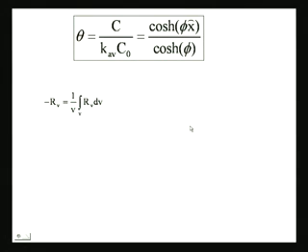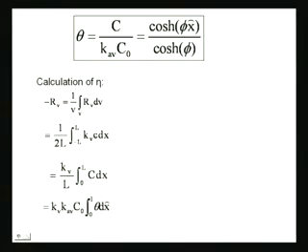We calculated eta, the effectiveness factor. So, the effectiveness factor is the reaction rate as it happens inside the matrix itself, which is the observed reaction rate, total reaction rate, actual reaction rate actually, not the intrinsic reaction rate, over the intrinsic reaction rate evaluated at the surface. Okay, that is how we had defined, if you remember, our eta.